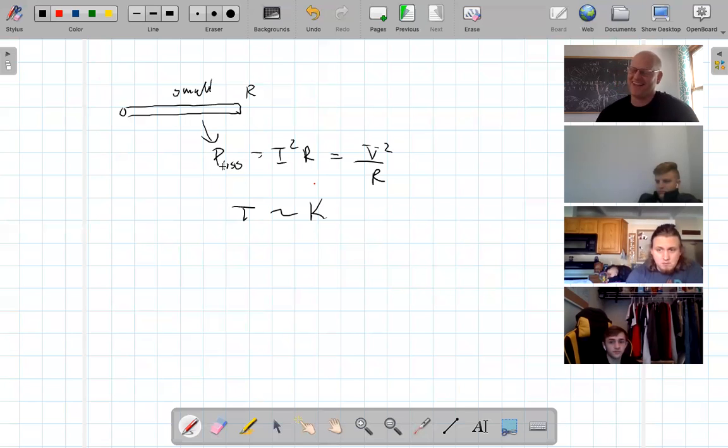Exactly. That's right. So what the breaker does is, for each wire that runs through your house, you have a different gauge of wire. Gauge of wire just refers to the radius of the wire. For higher gauges, that's a smaller radius. Smaller gauges, that's a bigger radius. So the bigger the radius is, the bigger the cross-sectional area is, which changes the resistance.